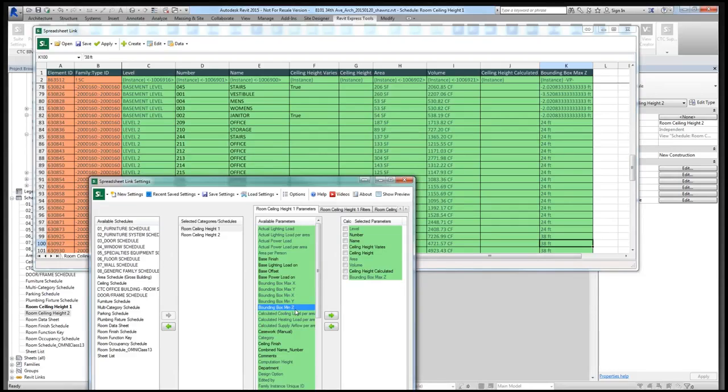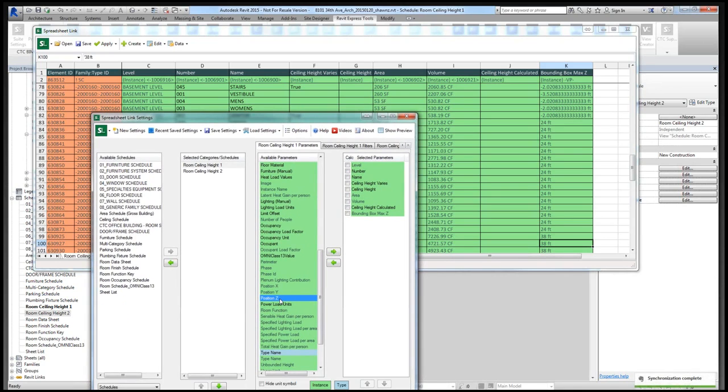The problem is that the physical boundary of the room isn't what I necessarily wanted, because what happened was when there was finished floors under the room, it would subtract just a little bit, like that 1/8 inch or that 1/4 inch, or there's a number of different things that can modify the bottom bounding box of a room. So I didn't want to use that one. What I wanted to use was the value that the room thought it was for its original insertion point, the position Z, where it was placed in 3D space.